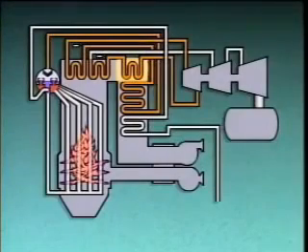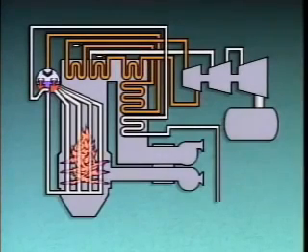For example, this boiler has a primary reheater that the steam enters first as it comes from the high pressure section of the turbine. After the steam flows through the primary reheater, it moves on to a secondary reheater. An attemperator, located at the beginning of the secondary reheater, is used to control the final temperature of the superheated steam leaving the secondary reheater. The attemperator sprays water into the steam flow if the steam gets too hot.